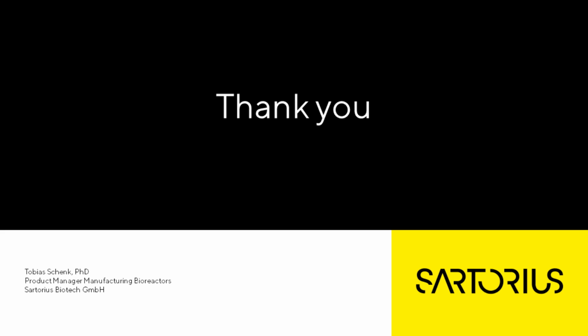So in the rocking motion reactors, you do have the possibility to control the pH due to our optical sensors. You can actively also influence the pH by adding ingredients to control the pH, or, and this is what most customers are doing, you do it via the cell culture media. So you add always a bit more new media, or you exchange the media completely if we talk about a shot-based perfusion, and the media itself has some pH buffering